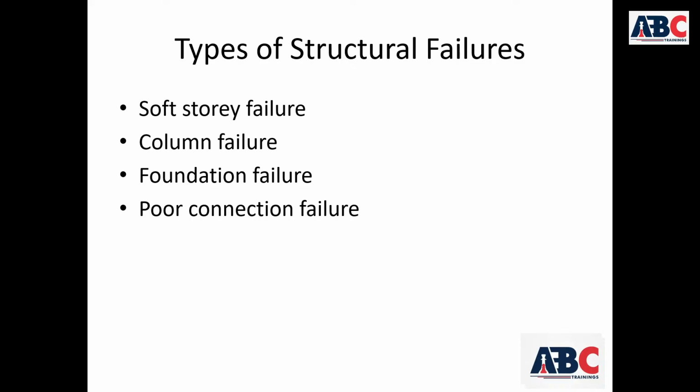During earthquakes, upper floors are stiff due to walls. Ground floor is extremely flexible and the entire lateral displacement concentrates at ground level. Columns at the ground floor experience excessive bending. Columns fail and the whole building collapses. This is called soft story collapse. Many buildings collapse in huge earthquakes due to the soft story effect.